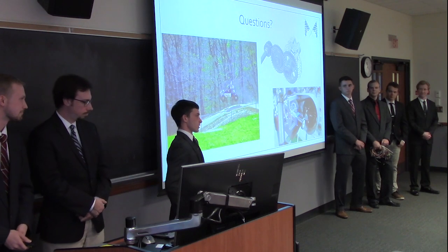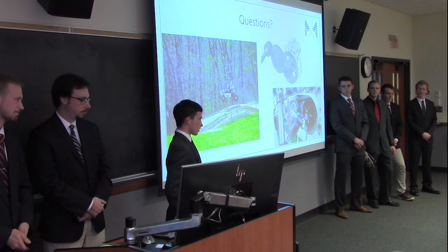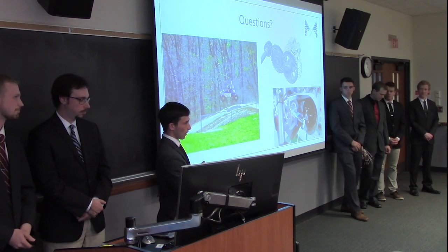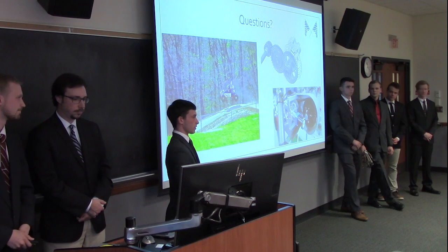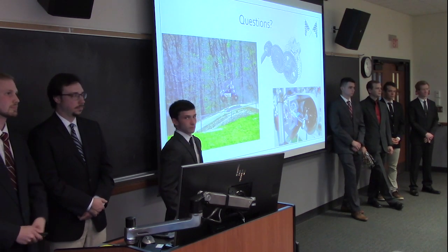We chose the 6061 over something like a 7075, which would be stronger, just because we didn't need the strength. We made it as thin as the rules would allow, and the cheaper material was strong enough. So, Brian, you had a question?